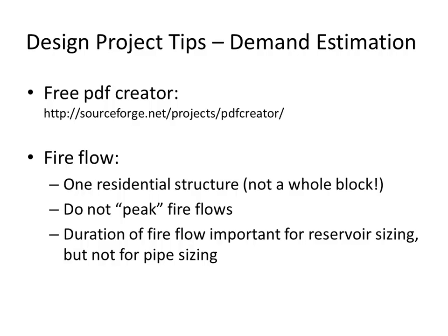The table bases fire flow on square footage of buildings and building construction. Would it be okay to use those values for there? Well, no, unless that table takes into account the material, like what it's made out of, and the spacing to other buildings. Because the NFF method that I've provided you the reference for does take those things into account. The square footage is one of the variables, the material, you know, whether it's wood or concrete or whatever, and then also adjacency to other structures. Yeah.